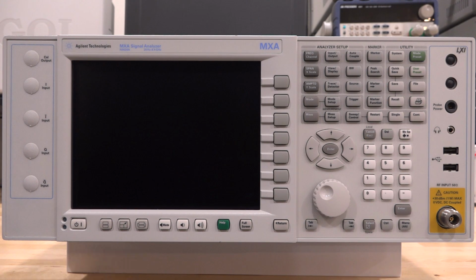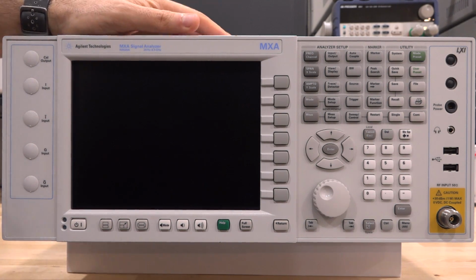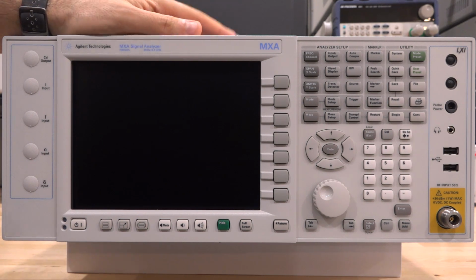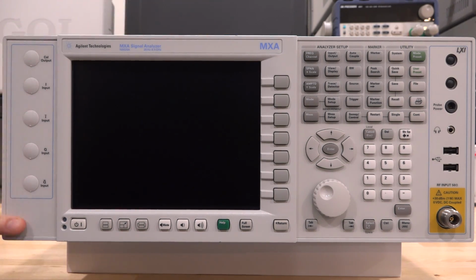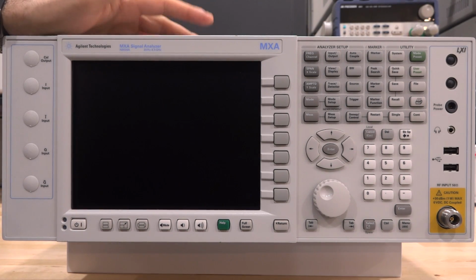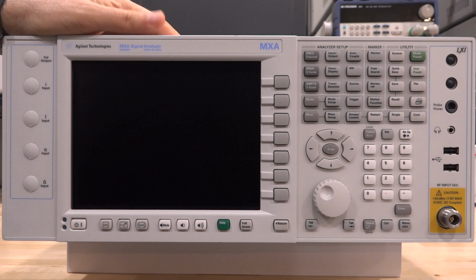In this episode, I have another product repair for you guys. This is an Agilent MXA signal analyzer N9020A. This one is a 20 Hz to 8.4 gigahertz unit. This is the MXA, a fairly valuable instrument, and this particular one is equipped with real-time at 40 megahertz analysis band with a whole bunch of other options in it. Unfortunately, it doesn't have the IQ input option. It doesn't have the mixer input option, but nonetheless, it's a very nice instrument, even though it doesn't go very high in frequency. So we'd like to fix it and recover its functionality.